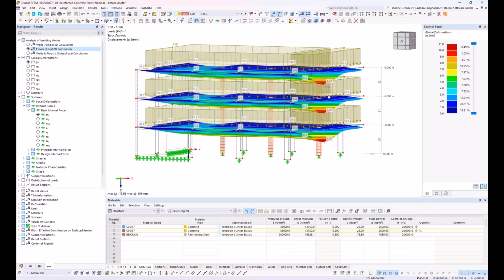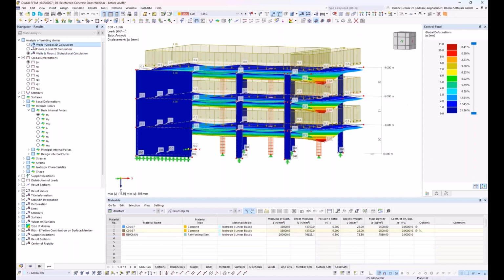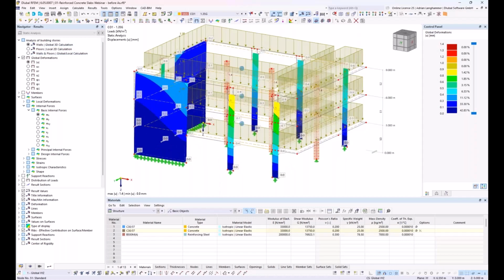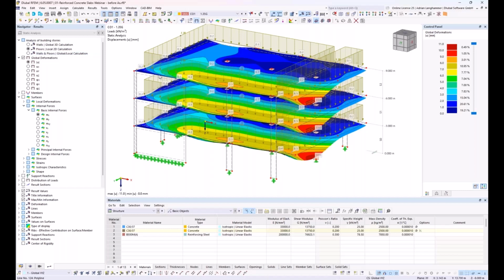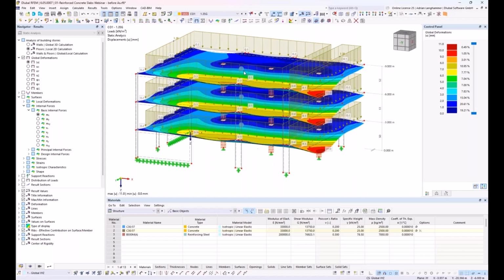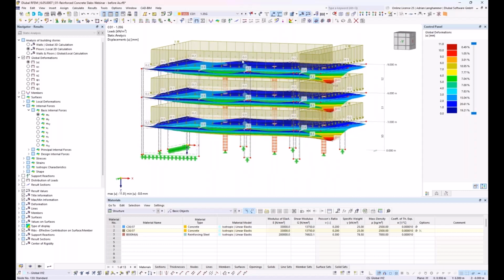I also will show another point. The program, as I mentioned, calculates the walls connected via rigid diaphragm, and the floors as, let's say, separated 2D positions, and it also calculates some load transfer based on a submodel which is calculated in the background.